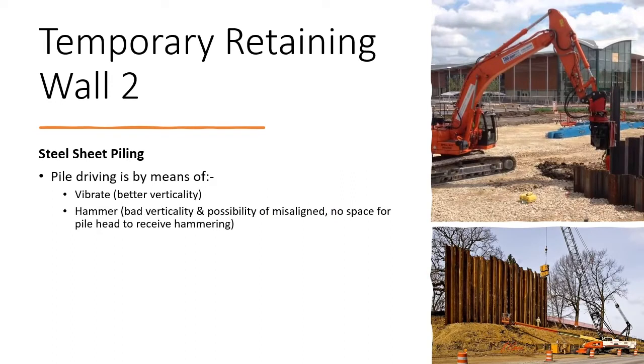To install sheet piling, we can do pile driving. One is by vibrating, which is better verticality. And another one is hammer. Okay, but it is bad for verticality and possibility of misaligned because no space for pile head to receive hammering.